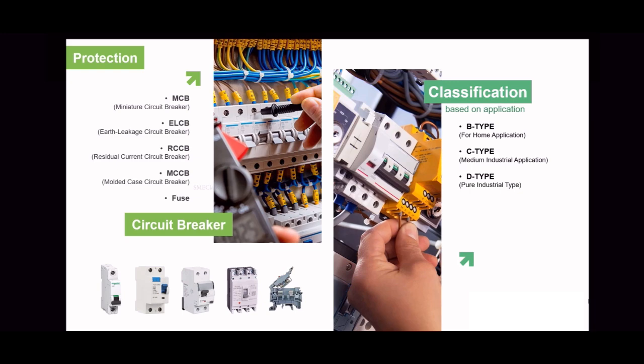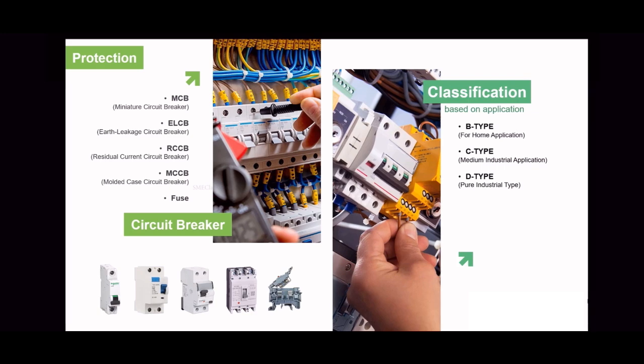That means in the case of MCB, you can see that 0 to 100 ampere is the fixed level. Like we have MCBs of 6 ampere, 10 ampere, then 16 ampere, 20 ampere, 25 ampere and 32 ampere. Likewise, there are different ratings. But in the case of MCCB, you can vary or adjust the rating of your circuit breaker.